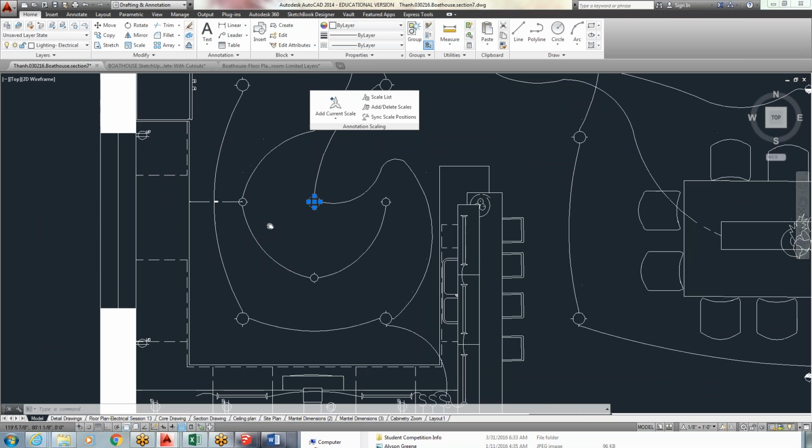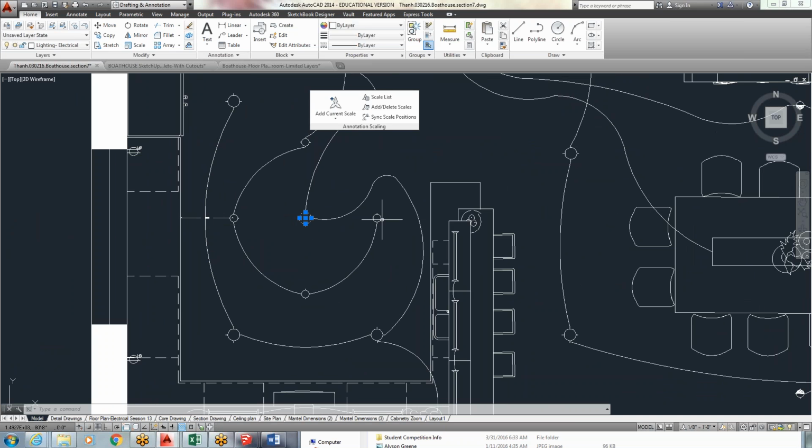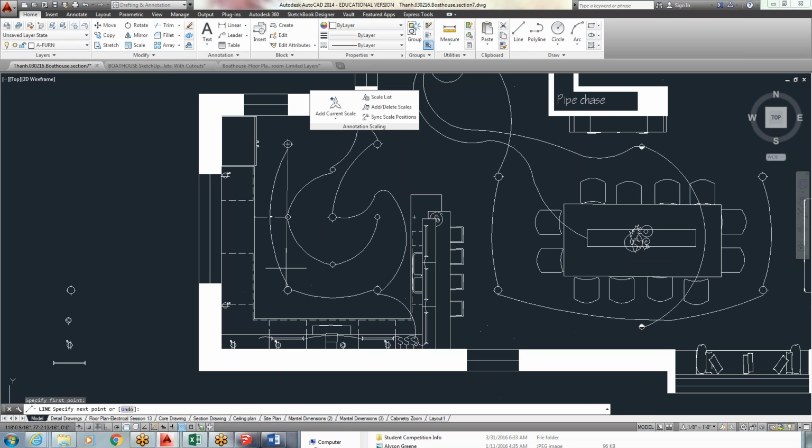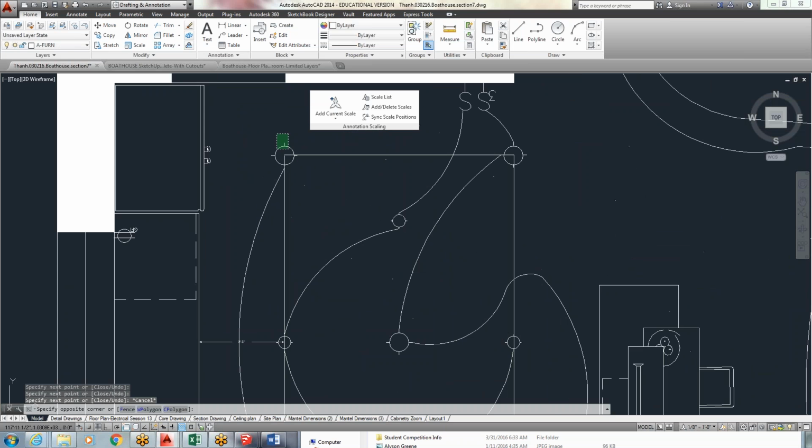I will be looking for not dimensions match, so I don't care. This could be 2 foot on this side and 2'4". I want to see it's mostly centered if that's your plan for your lighting. I will be looking to see that you understand lights are usually lined up in certain situations. So like these perimeter lights do line up with each other from center. If I snap to the center of this light and to this light, these 3 all line up. These line up across to make a nice rectangle. So there should be some straightness. I don't want to see this.